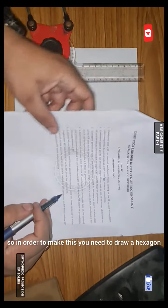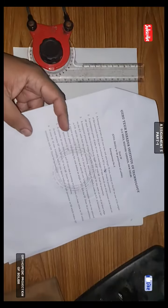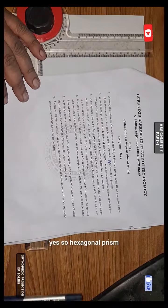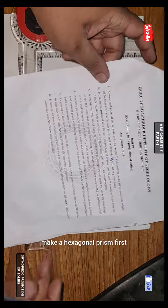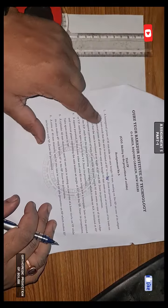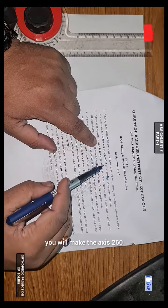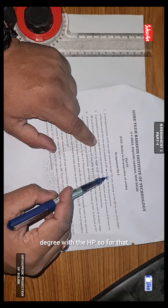So in order to make this, you need to draw a hexagon. So you need to make a hexagonal prism first, then you will make the axis 60 degrees with the HP.